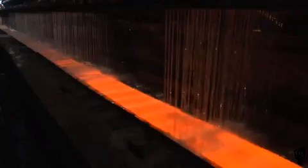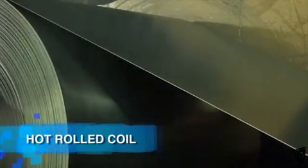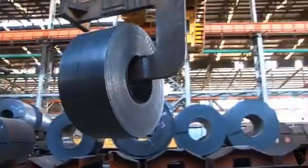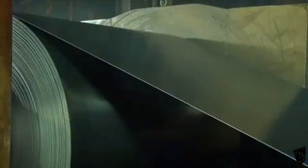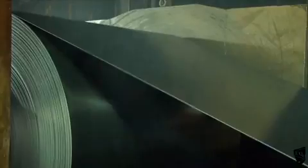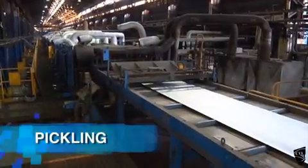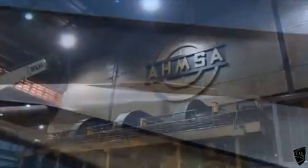At the end of the hot strip line, there is a cooling system and a coiler. Hot-rolled coil, also known as full hard coil, is shipped directly to the customer or sent to other processes in the AMSA cold rolling departments. Through cold rolling, the thickness of the sheet is reduced, while at the same time modifying and enhancing its physical properties. The process begins with pickling in order to eliminate oxides through the use of a hydrochloric acid-based solution.